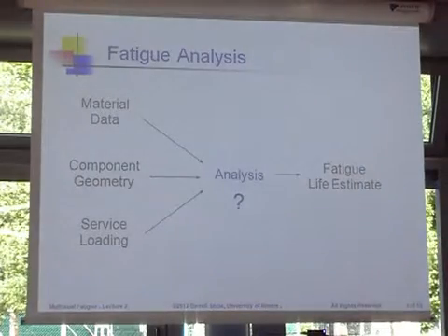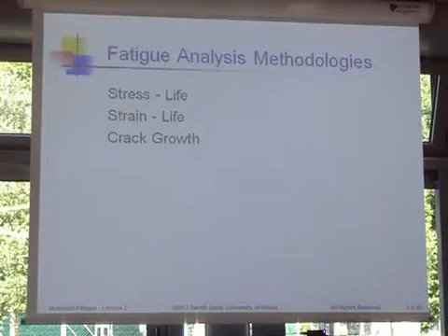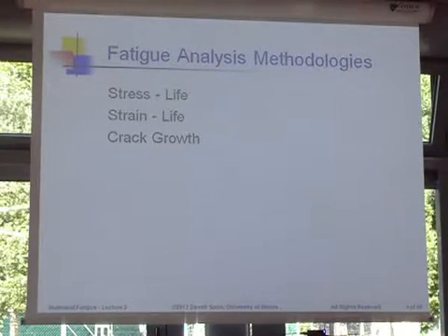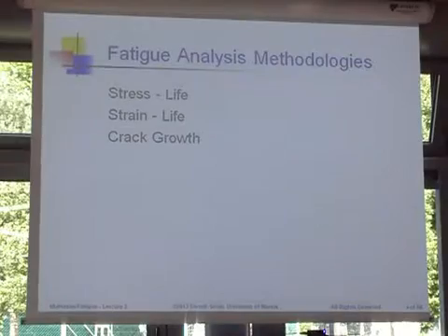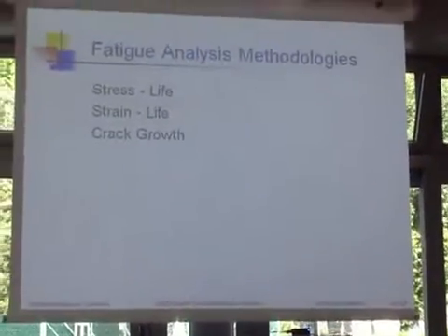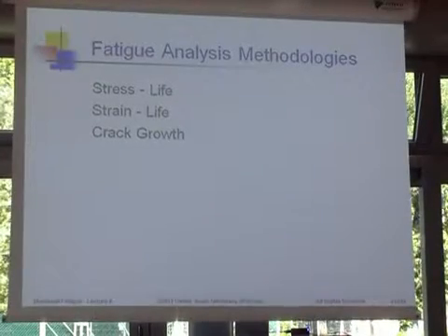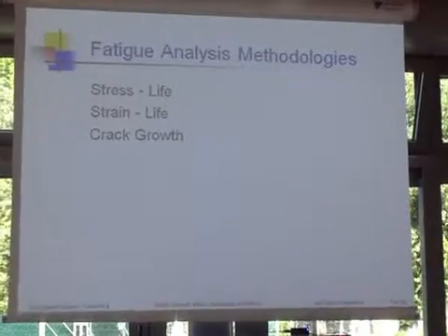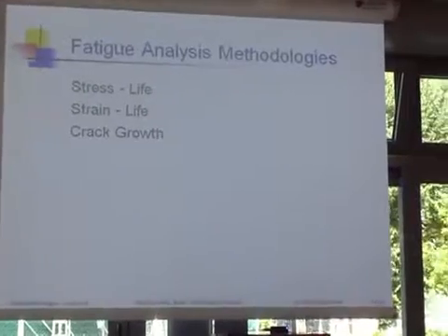And the terminology I like to use for the different ones is I like to think about lumping all the things that are based on stresses as the driving force to be the stress life approach, and all those that are based on using the strains rather than the stresses, strain life. And then, of course, we might consider fracture mechanics and crack growth directly.